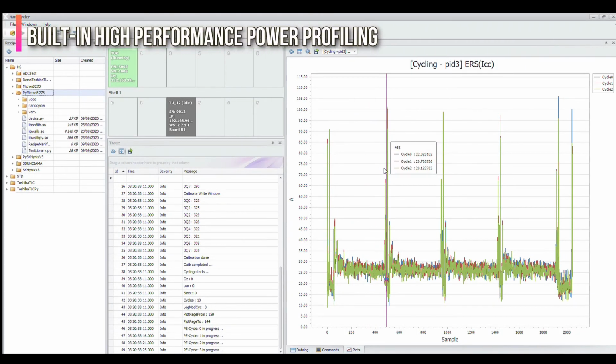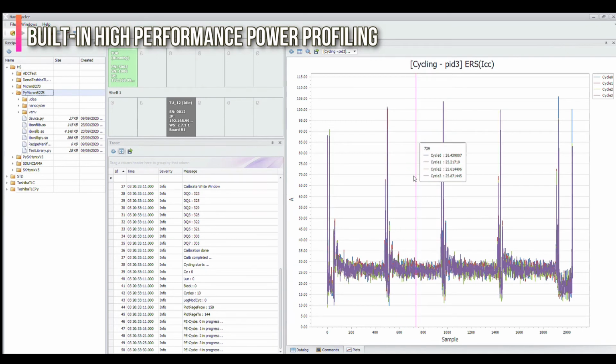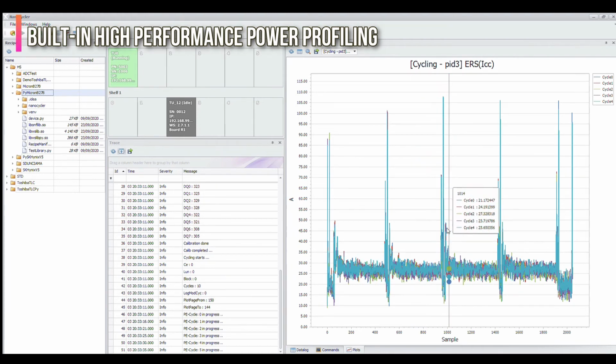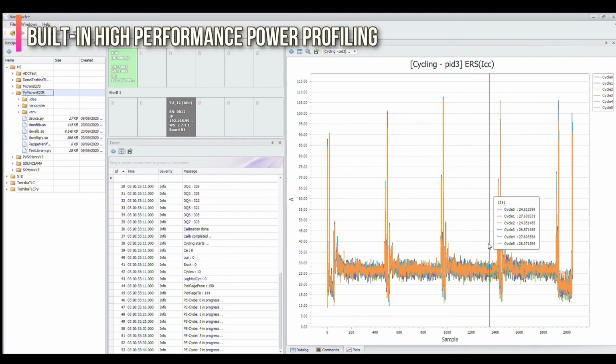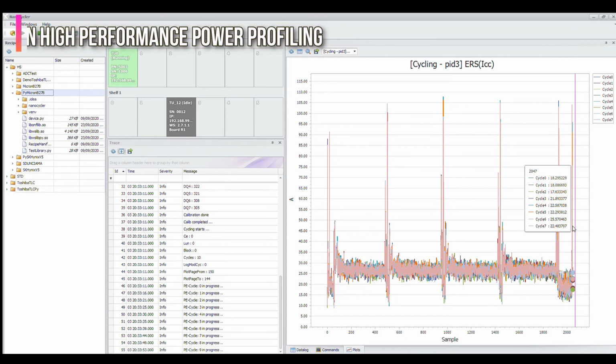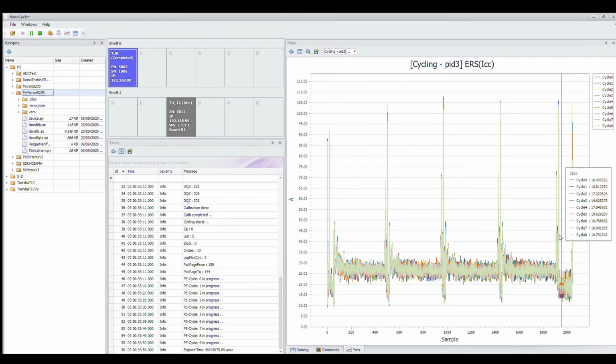Nanocycler captures the power consumption for each supply at 50 nanoseconds sampling rate with 1 mA resolution. Flash operations power consumption data are processed in real time to provide high-resolution current consumption waveforms and key metrics, peak, average distributions over a long period of time. Several customers reported that this feature was an essential help in designing the SSD power subsystem.